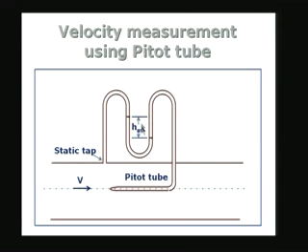So, the difference here, Hm, is the manometric height which is measured here, and is convertible to a delta p. Delta p, which is measured by this head Hm, is nothing but the difference in pressure between the stagnation point and the static pressure at the wall. You see now what we are doing: we are converting the velocity into an increased pressure at the stagnation point. This increase in pressure is because V is going to be brought to 0. So, this process is called the stagnation process. The velocity V is going to become 0 at the stagnation point here, and therefore, along the streamline, if you apply the Bernoulli principle, the pressure is going to continuously increase and become equal to the stagnation pressure at the stagnation point, and the velocity is going to be 0 at that particular point.